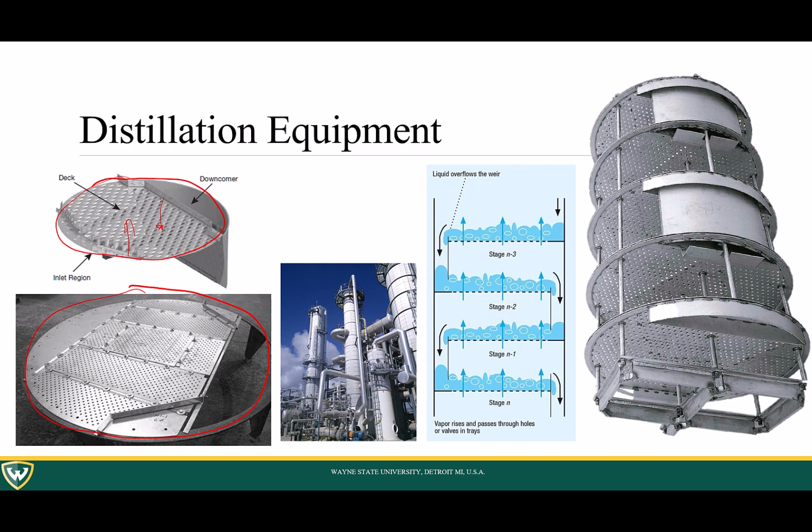There's going to be intimate contact with each other such that you're getting that heat exchange that we talked about previously. Here you would get some frothy, bubbly mixture where some of the gas is getting entrapped by the liquid, some of the liquid is getting pulled up with the gas and being vaporized, and you get that intimate, long exchange, such that you have efficient heat transfer, and you could assume that each liquid and each vapor leaving the stage is in equilibrium with each other.